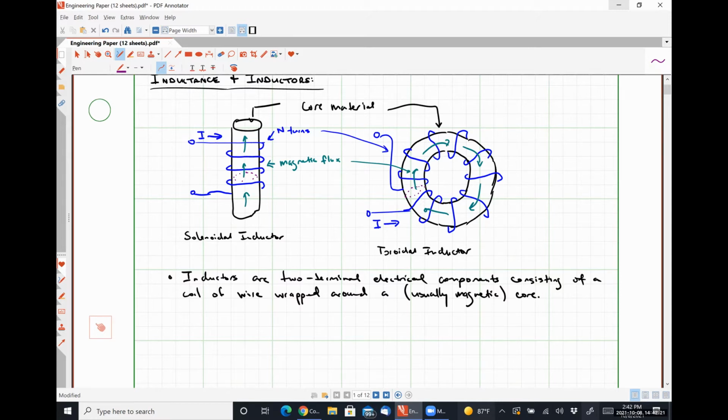Okay. So another place that inductors are used is electric motors. They're a huge portion of electric motors. Probably my favorite place that inductors are used are in electric guitars. The pickup of an electric guitar is nothing more than an inductor with lots of magnetic core material. And so what it does is it magnetizes the string. And as that string vibrates, the coil picks up that changing magnetic field of the magnetized string and creates a voltage signal, which then gets amplified. And that's why we have Metallica and Slipknot and all that kind of good stuff.